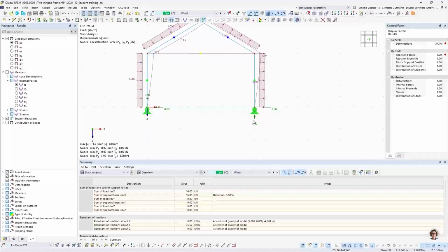And that leads to a force pair, a compression support reaction on the right and a lifting support reaction on the left. So yeah, this is interesting because you might need to design the connection for the left side accordingly. So it can bear not only compression forces, but also lifting forces.